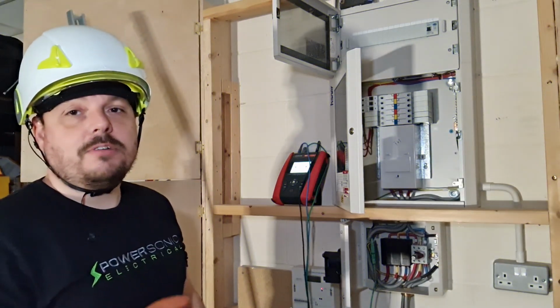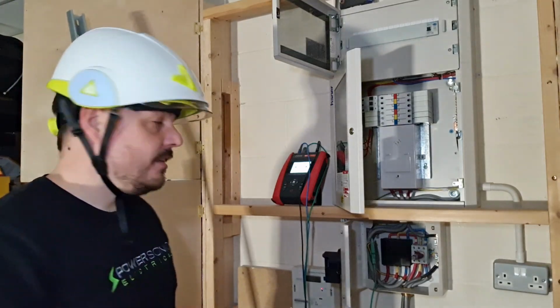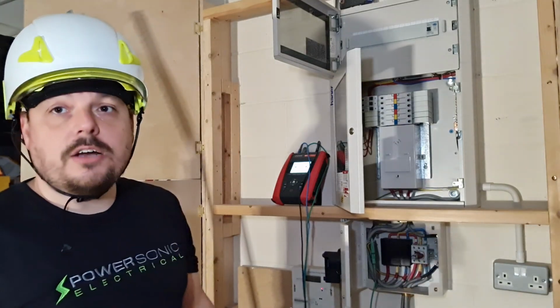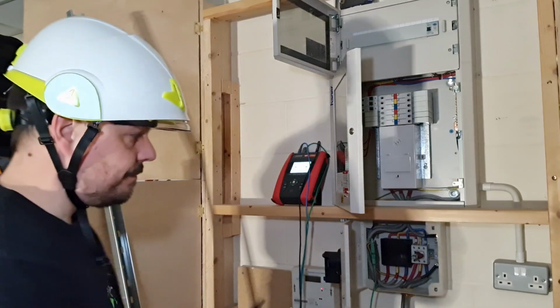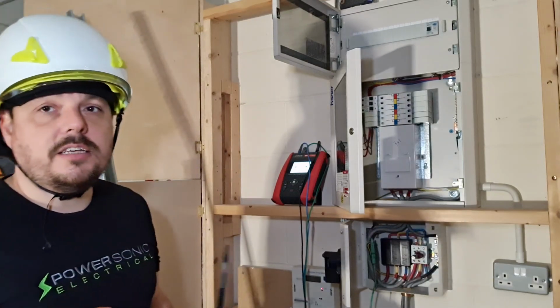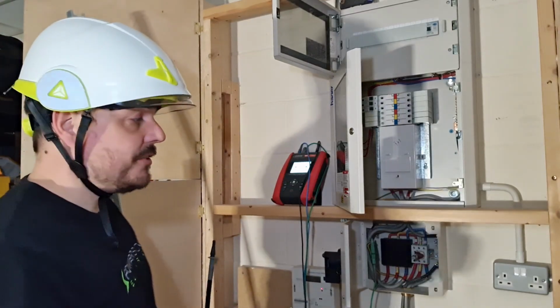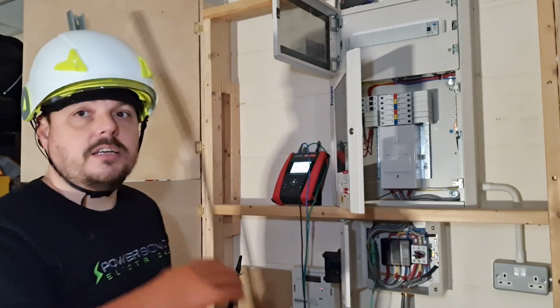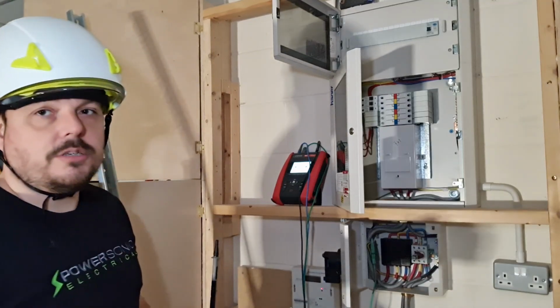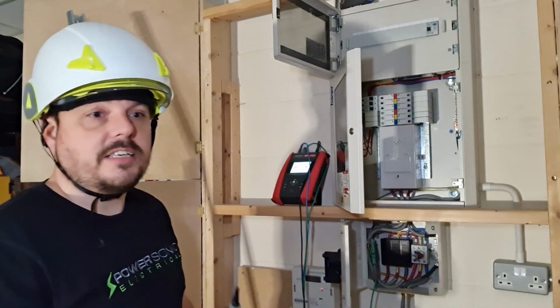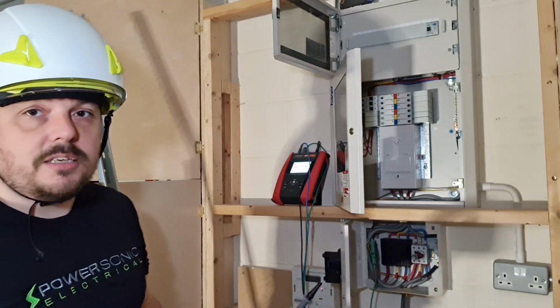Okay, so I'm all set up now, ready to perform the ZE measurement. Obviously we need to do that on all 3 phases in this instance, and if I wanted to get the value of PSC and PEFC, we could do that at the intake by measuring onto the neutral as well, but I'm not going to do this in this experiment. I just want to know what the ZE is, so we can play around with some calculations later on.